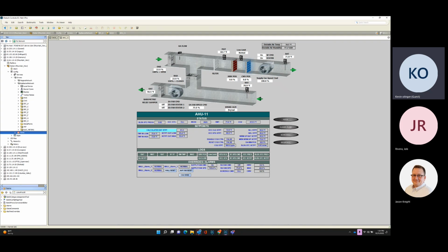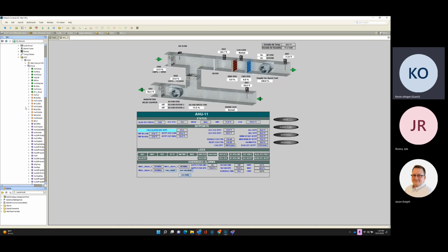But when the fire system goes into a full-fledged fire alarm, we typically through the DDC have a point where the fire system closes or opens a set of contacts to the DDC. The DDC sees that as a fire alarm, and then via software shuts down all of the air handlers, all the rooftops. Are you aware of any of those types of logics taking place?